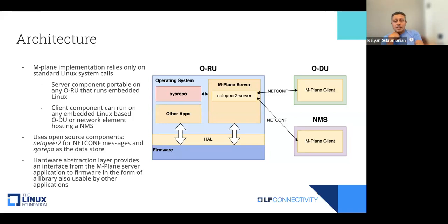And then we also leverage sysrepo, which is another key open source contribution, again, by a variety of people, all under the standard Linux umbrella. So any embedded system that runs embedded Linux can host these bits and pieces, right? And all we've done is glue them together with this little magic called the HAL, right? And sysrepo, again, I wanted to call that out. It's really an embedded database. This embedded database is extremely flexible and powerful. You can enable and disable as many modules as you want. It has all the standard ACID properties of any large database system that you might be used to. So the usage from a query and setup perspective is super easy. If you're used to running even large scale databases, you'll find this a breeze.